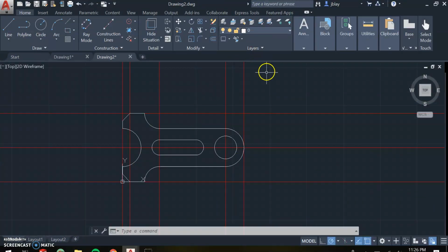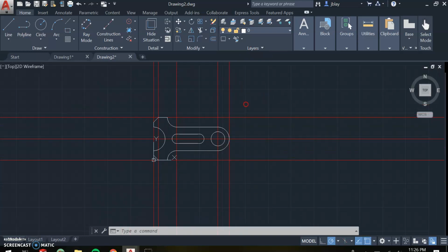And what I'll do is I want to make these construction lines not visible, at least for a second, so that I can do my center lines and center marks in peace. So I'm going to click this drop down here. And this is a way to be able to see all the different line types that you're drawing with. So over here where it says 0 and there's this white, this is the layer we're drawing in. So that's this white stuff that everything's drawn in. And then below we have our construction line layer.